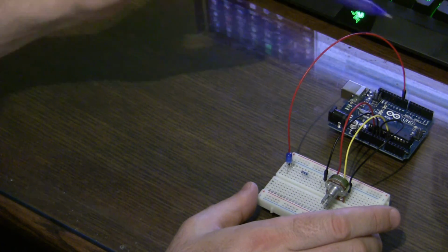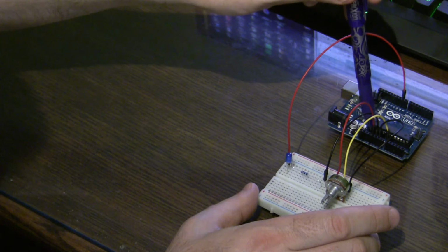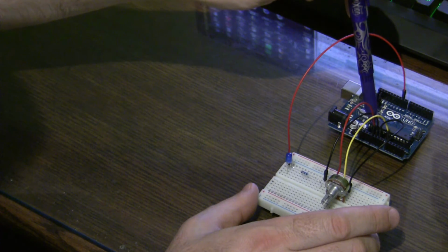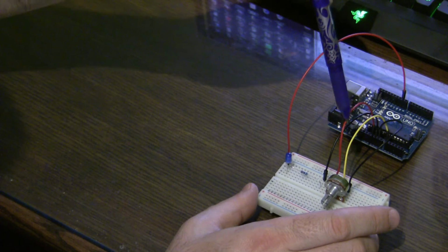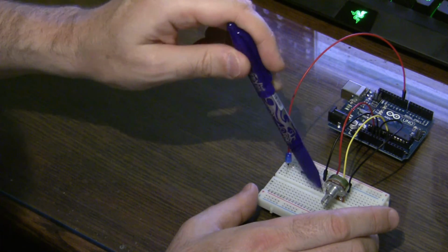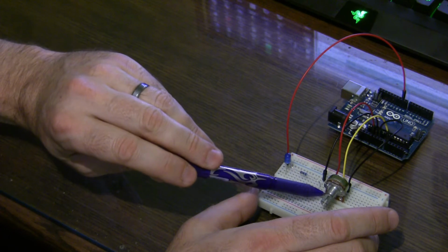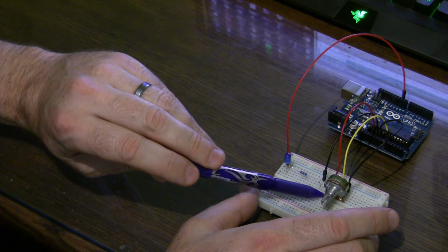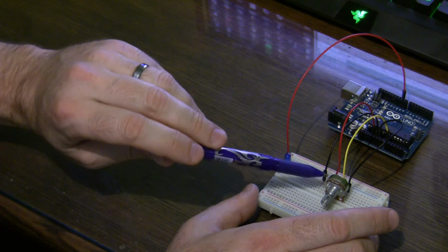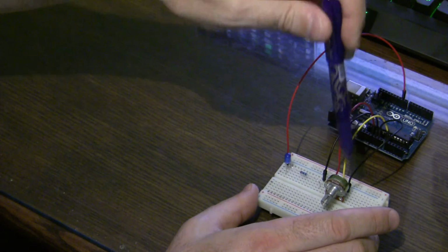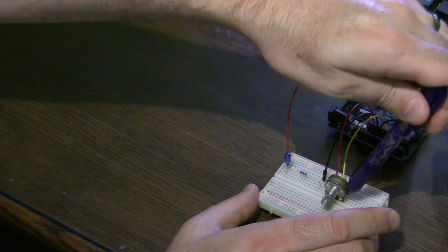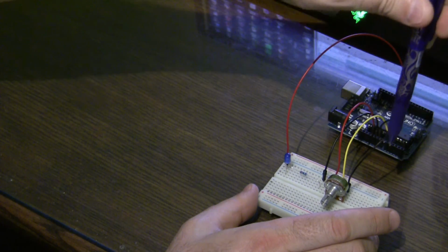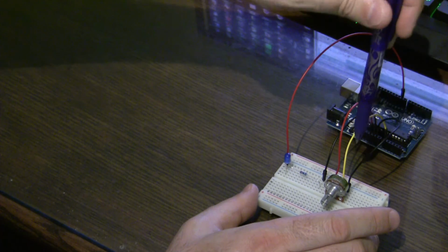Now our other circuit, we're using the 5 volt pin on the Arduino here. That's where this red cable comes from. That's in the same row as one of the pins on the variable resistor. The power is going to flow through this. It will come out the other end, connected to the same row as the pin on the far end is the black one, and that goes to ground.